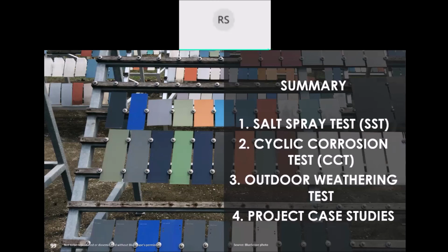And lastly, you can ask for case studies of that same specification in, say, near the sea. If they can't provide you, that means either they don't have a material that can last, that spec itself cannot last that long in that environment, or they have not done such tests. And you can always push for it, so that eventually this data is available for you to make an informed judgment.